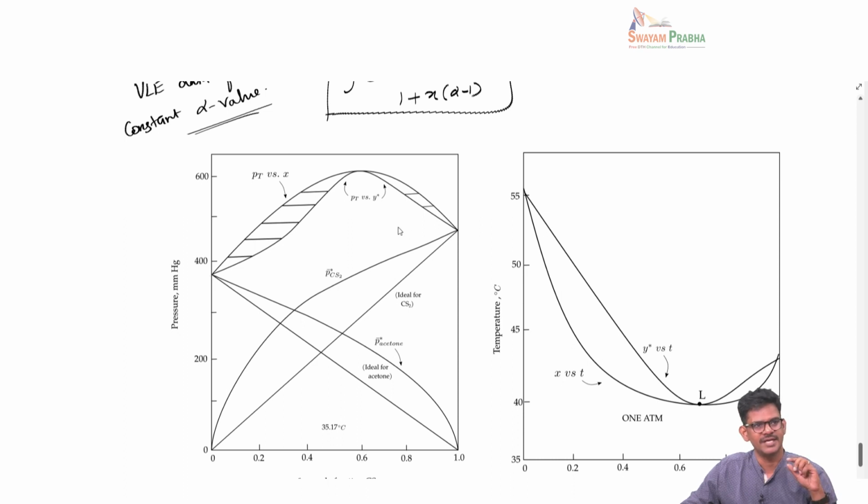What it means is that there could be compositions where the mixtures are boiling at a vapor pressure higher than the two pure component vapor pressures. The consequence of this can be shown in the TXY diagram, which is on the right. You should be getting the envelope between TB and TA in principle, but actually you see that there are temperatures which are below TA.